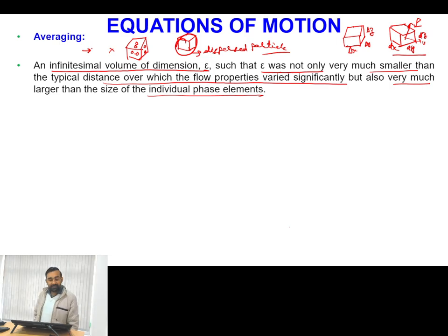Initially we will start with this. In case of separated flow, whenever you are referring to a control volume here and here, you need not go for multi-phase equations. You can simply solve this using the single phase equation. But when your control volume is near the interface, there you will have the multi-phase mixture present. So the multi-phase equations will be applicable only for the control volumes which are holding the interfacial boundary, and for all other cases the single phase equations will be valid.